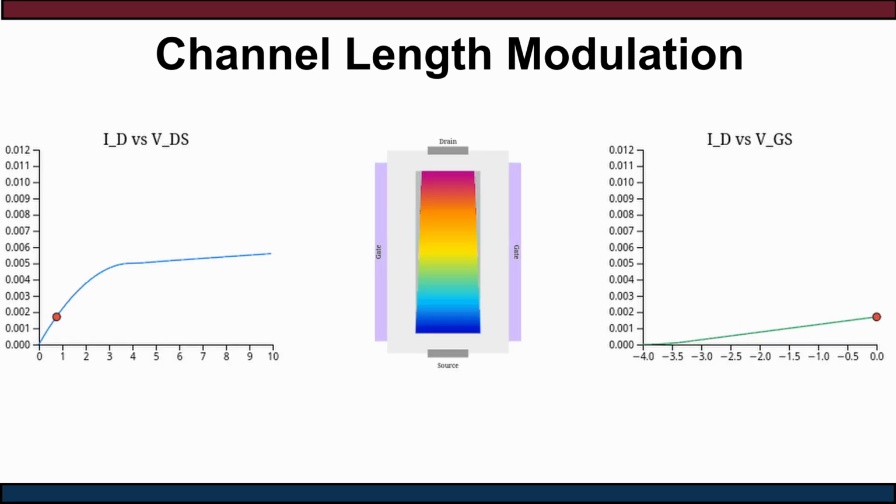My description has significant disadvantages. To understand that, we can play with an interactive graph that represents the dependencies of values in the transistor operation. Set the gate source and drain source voltage to 0. In the representation of the transistor, we can observe a colorful channel. Color represents the electric potential at each point.